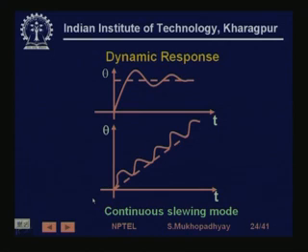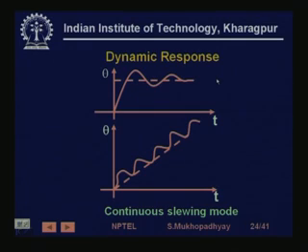Now, generally when we are using a motor, we want to move it as fast as possible. If you are giving pulses slowly, then what will happen is that you excite one phase, the rotor will come and stand still. It will actually stop at that position. Because of its inertia, it might give a little overshoot, but it will stop. But if you let it stop and then excite, then you are taking more time, right.